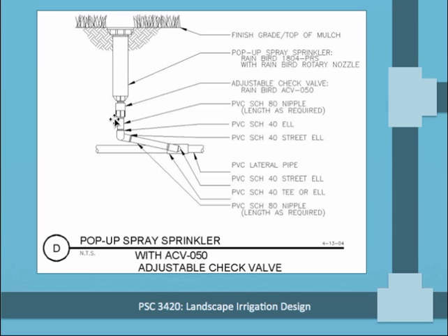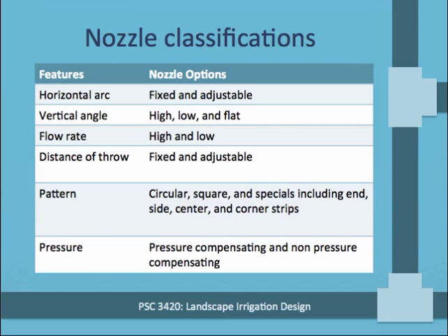If you don't have something like that in place, then it's absolutely normal that all of the water in the system is going to drain to that low point, and the pressure will typically overwhelm the sprinkler assembly here, without a check valve that is, and create a lot of ponding or puddling in the area. So they're a good thing to have, at least on those heads that are lower in elevation.